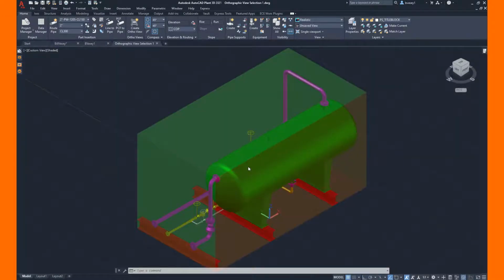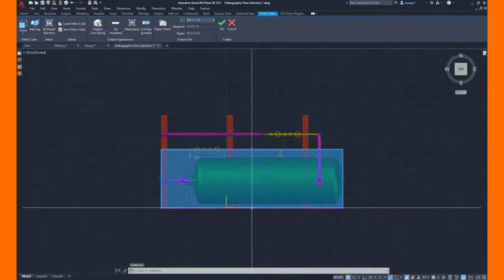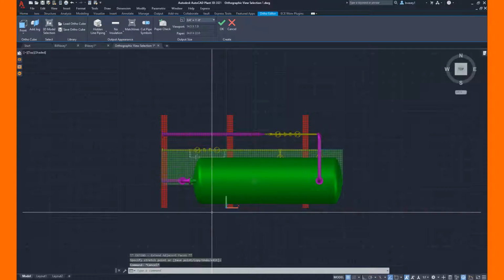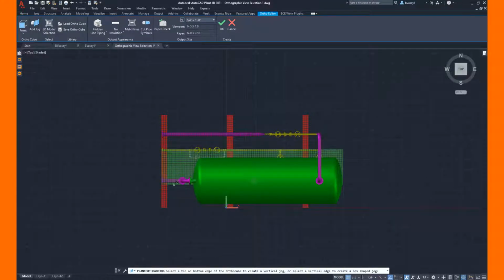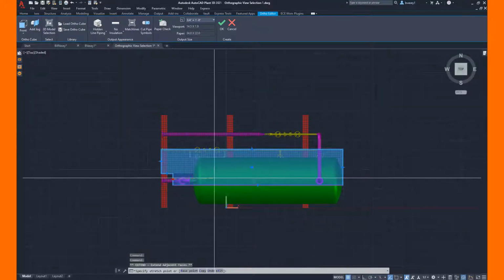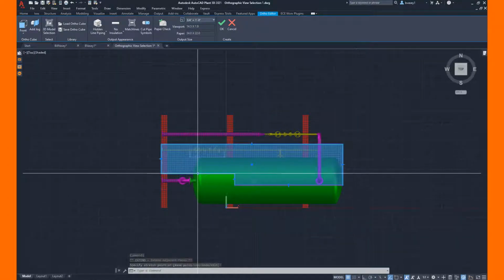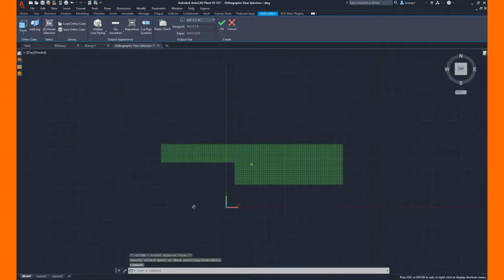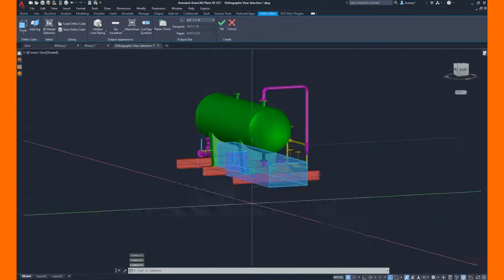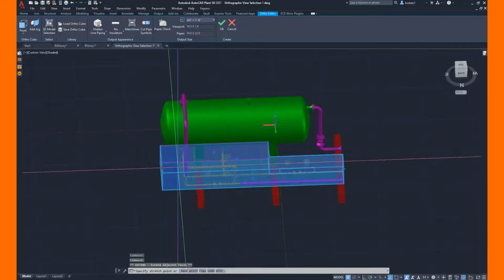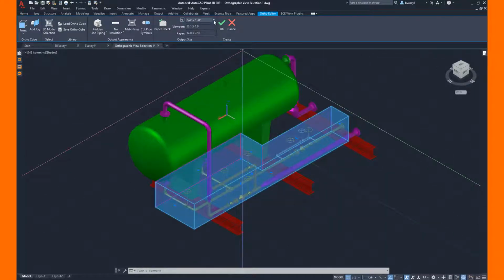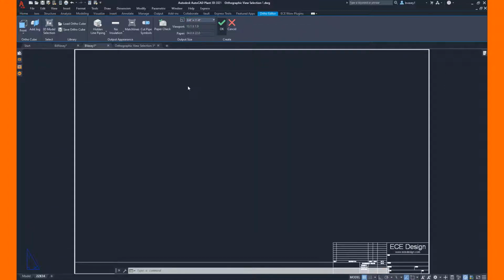And here it's empty. We go into an orthographic view setting mode where we can adjust a view box, do things like add a custom section, adjust that section so it envelopes the pipe that we're going after. This pipe run is again 1205. A little final adjustment on the end here, and we'll go ahead and check our scale. Everything's going to fit on my D-size drawing, so we'll go ahead and start the placement of that front view.